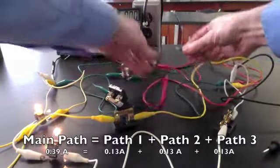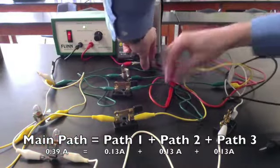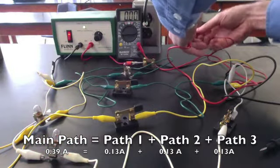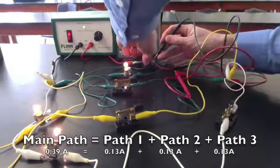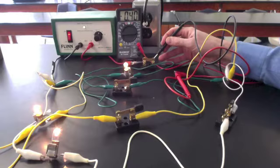Combined, 0.13 plus 0.13 plus 0.13 is 0.39 amps. The main path has a current of 0.4 amps. So in this parallel circuit, the voltage was remaining around 6 volts, but the current was increasing every time you added a path.